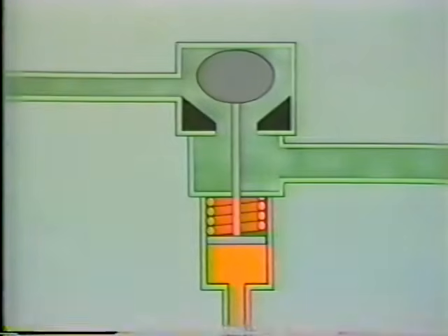When the turbine is tripped, the hydraulic oil is quickly bled from underneath the piston. As this happens, the spring expands, forcing the valve disc back on its seat.